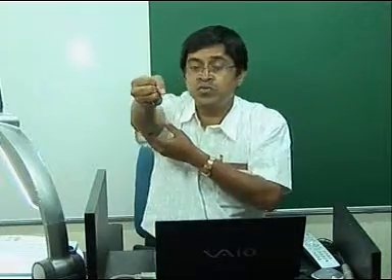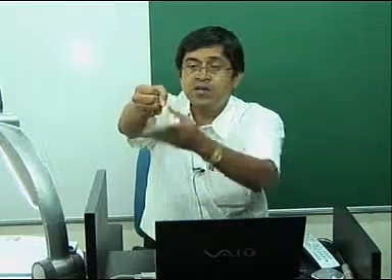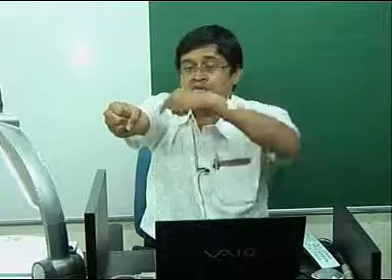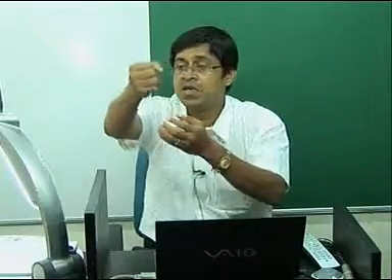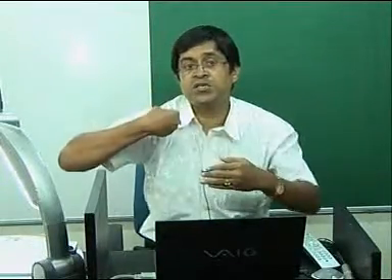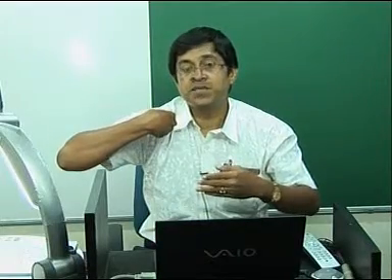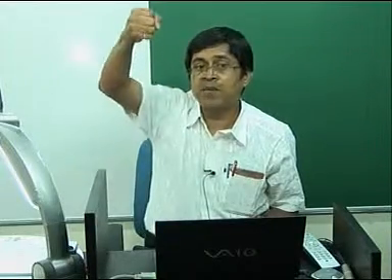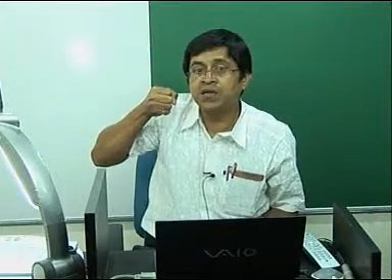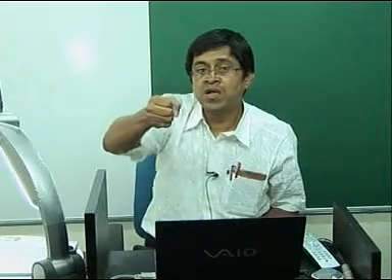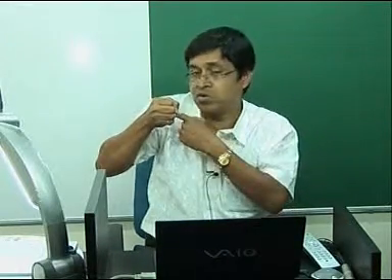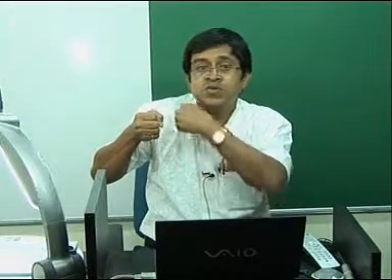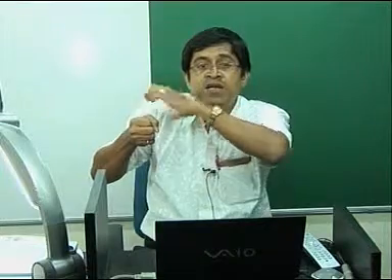Whichever robot you see, this is the gripper. With the cylindrical robot, you cannot go more than a certain distance. One of the simplest cases is, if the end effector cannot reach this space, you will create a hollow. For example, the cylindrical robot can go up and down, and it can slide close and far. But how close? It cannot go to my axis. It can go up to this much, so this much will be a hollow workspace.